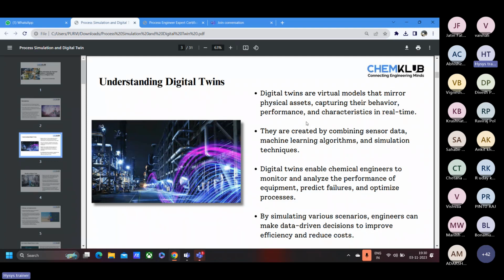for example, it will show you the chart of your efficiency, that yesterday it was performing at 70 percent, today it is performing at around 72 percent. So what changes have you made, how are you getting higher performance, or why are you getting lower performance. This is how the digital twin works. For example, the Aspen model of your compressor, along with the real feeding of real-time data directly from the plant, and that model will run in the background on a day-to-day basis, and then it will provide you all the analytics required in order to optimize that equipment.